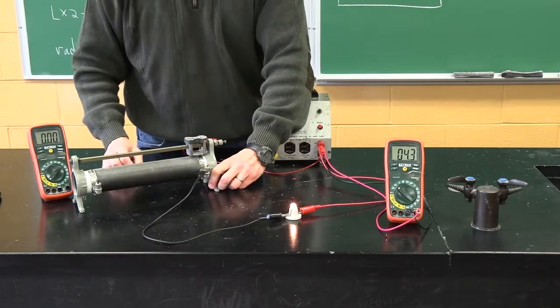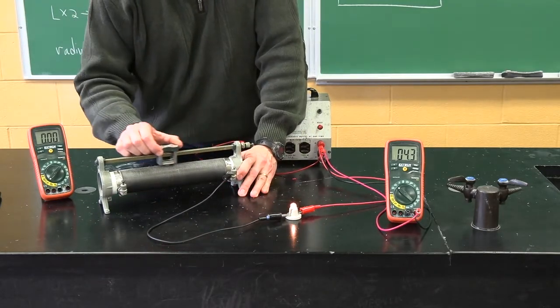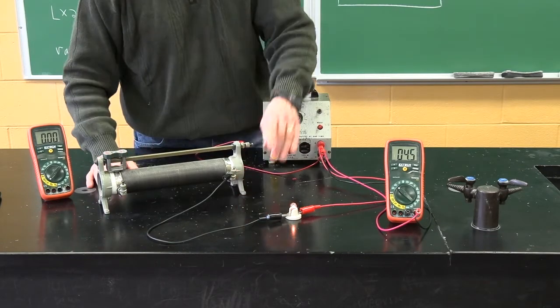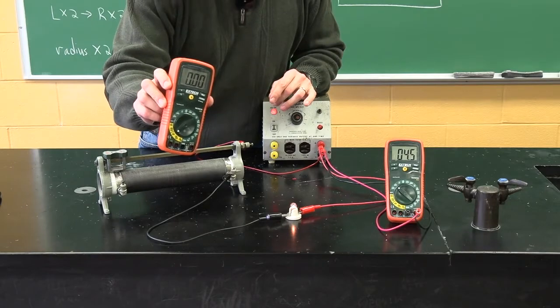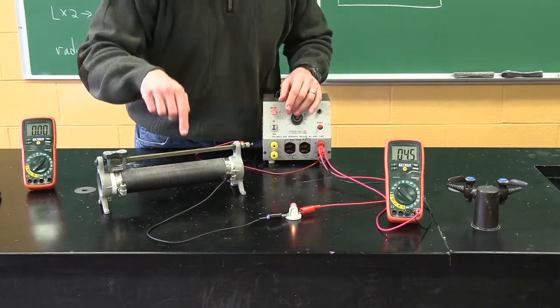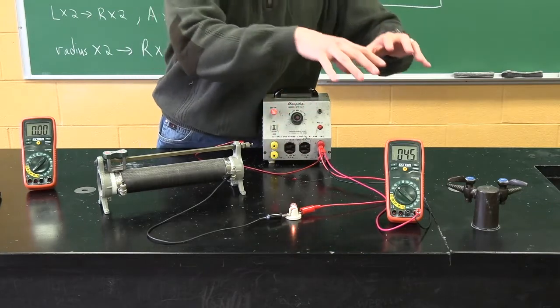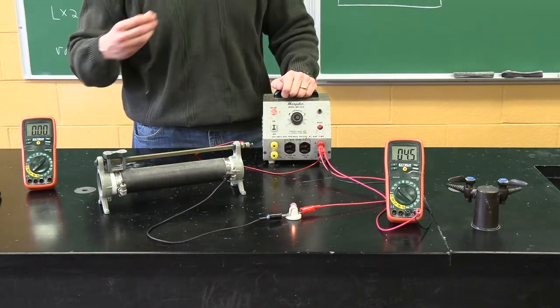We see this is very little resistance, and I'm going to add more resistance, and you see the bulb brightness goes down. So more resistance, we would have seen less current if I had the ammeter there. We see that through the bulb brightness. More resistance, less current, more voltage, more current. So now we're going to put those together into an equation called Ohm's law.